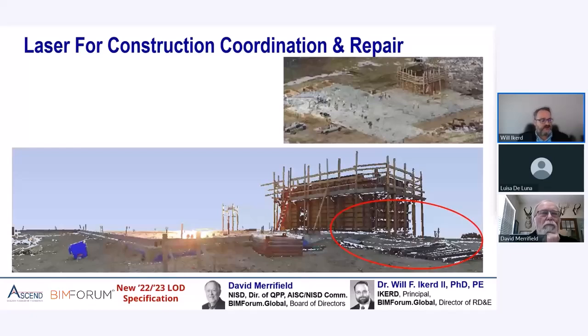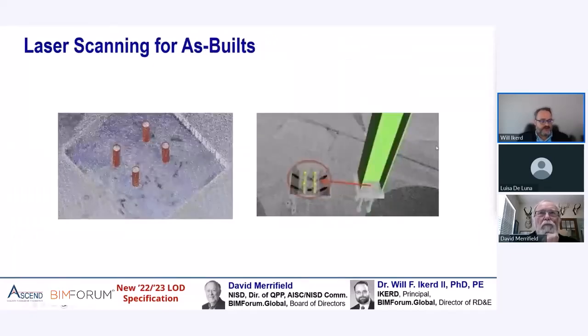These turn into like little trash cans over your entire job site. There are also buckets that collect water when it rains. And laser scanning can't see through trash, nor can it see through water. It will reflect off the water. So if you are thinking about using this kind of approach on your projects, you need to consider who is cleaning out these column base plate pockets and who's vacuuming them or getting water out of them, because that's a frequent problem.